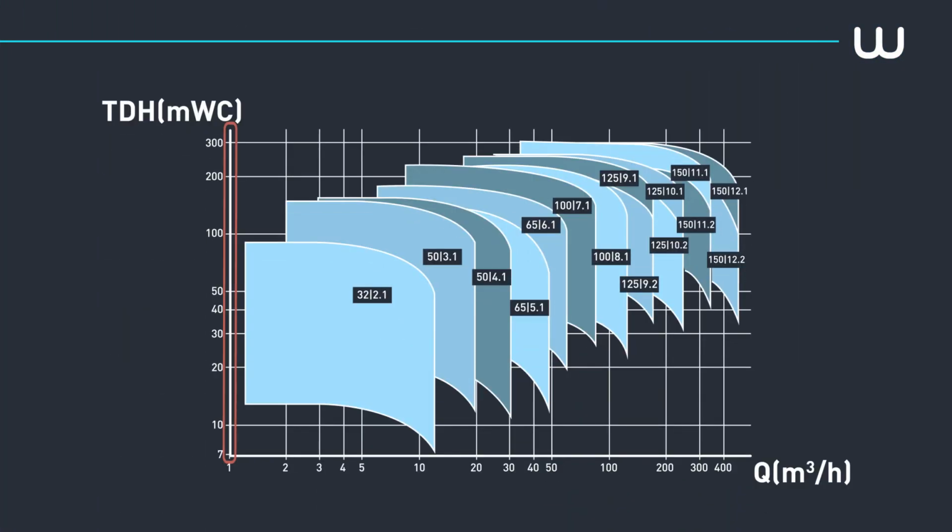When choosing a pump, it is essential to know the operating flow and the TDH required to transport water along the length of the discharge pipe. Pump suppliers possess summary graphs presenting the global flow, TDH operating ranges for several technical variants of a same pump model. On this graph, the TDH is placed on the y-axis and the flow on the x-axis. In the case of pump variations, the operating ranges are represented by polygons.